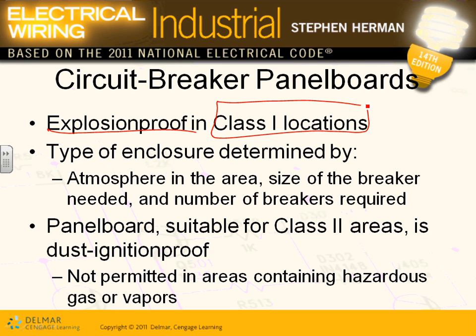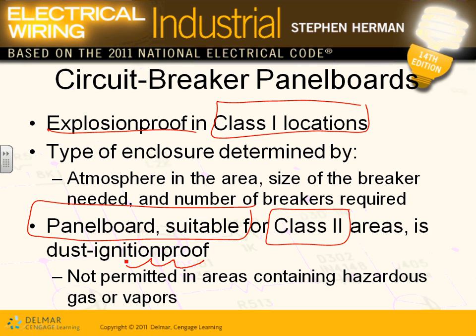Panel suitable for Class 2 areas. If you are to put a panel with the circuit breakers inside it in a Class 2 location, the key word here is dust ignition proof.